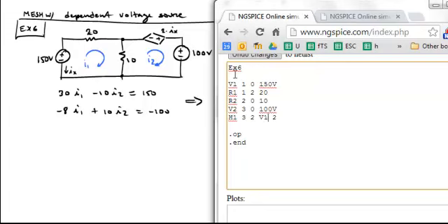You'd give the voltage source a value of 0 volts. So it wouldn't affect the circuit, but now it gives SPICE a voltage source from which it can grab a current, which it uses as the controlling current. Okay, so we are finished describing this. We're going to simulate.